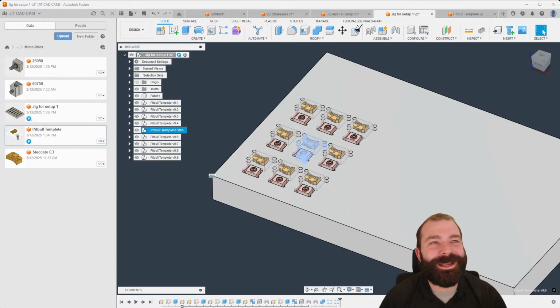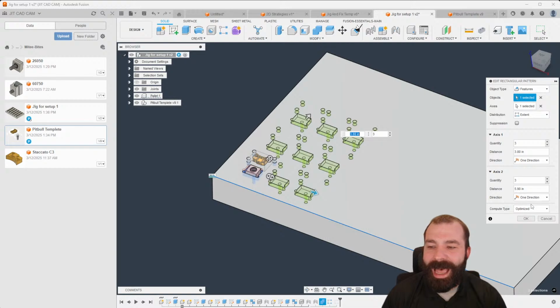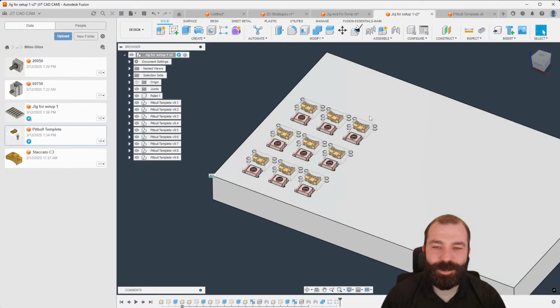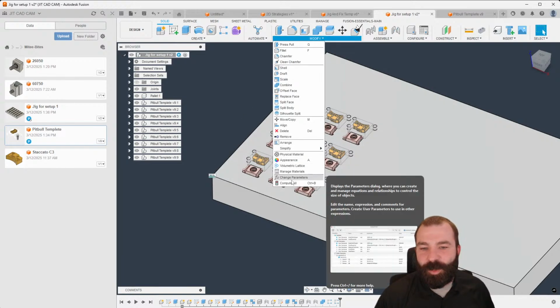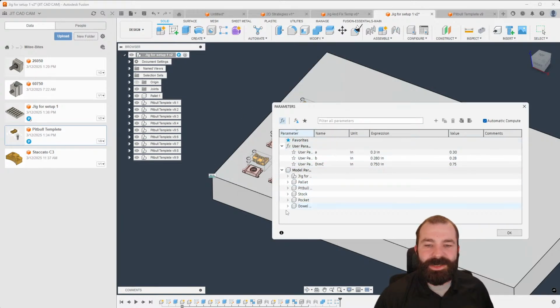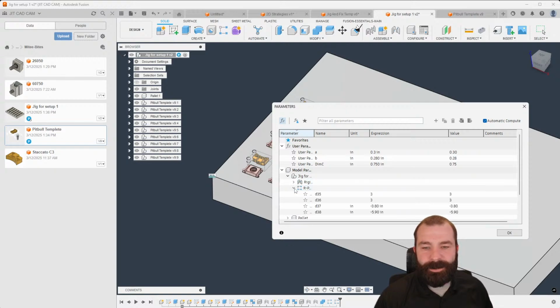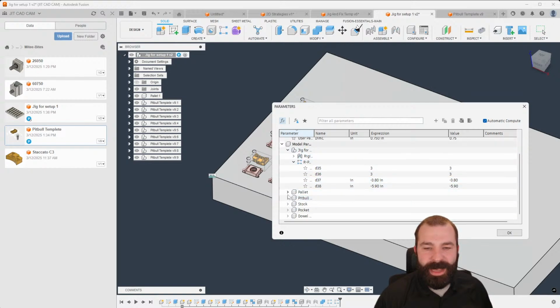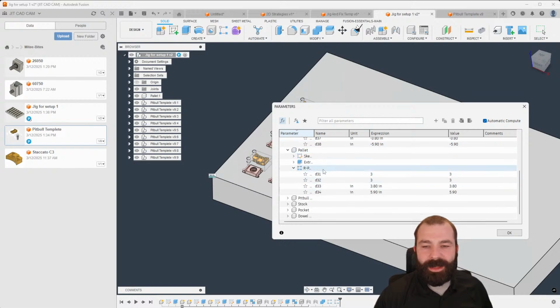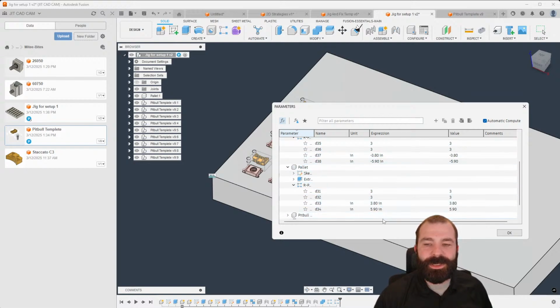And for anybody watching right now, you're probably curious, yes, it was me when we made that video and we did that pattern. Optimize actually fixed all of our problems with creating the locations. Now, Elijah, you could take it one step further, which is kind of cool, just so you know: if we go into our parameters table, again, we created that actual pattern, right? So whatever our pattern and our spacing was for the jig, and then you also have the pattern in here somewhere for the pallet, we can go ahead and plug in those numbers and carry them across both patterns so that you don't have to change it in two places, you can change it in one.